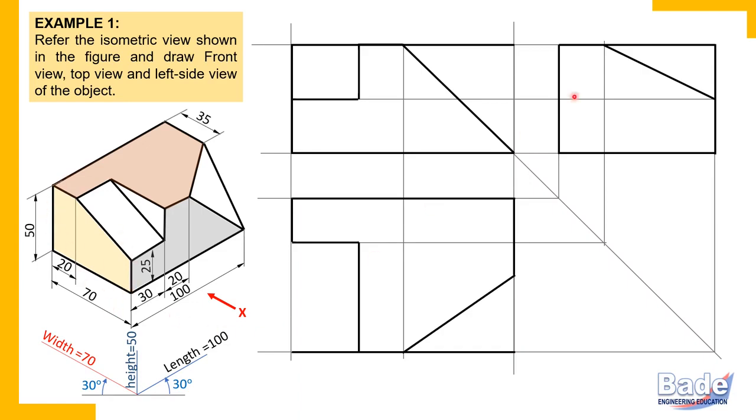Okay. Now, all the three principal surfaces we have completed. But wait, there is one more principal surface. This triangular surface. So now we'll draw this principal surface first, you should complete. This triangular surface has an edge parallel to width and an edge parallel to height. So two principal edges perpendicular to each other. Length and height.